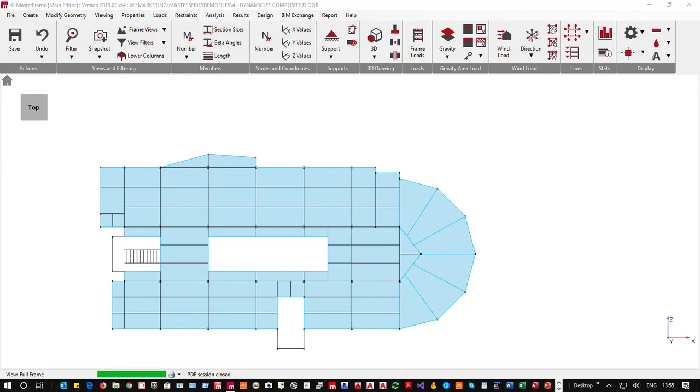This is a lot more accurate, and it is all about what this publication, P354, is about. It is about the accelerations that the user feels while walking and standing. It's not about the frequencies. So it's a lot more accurate, it's a newer science, and it is better.